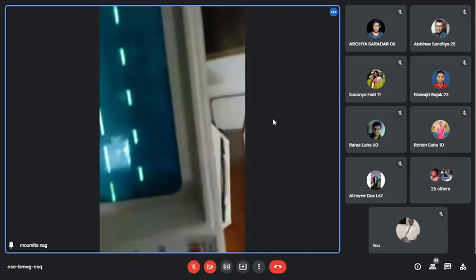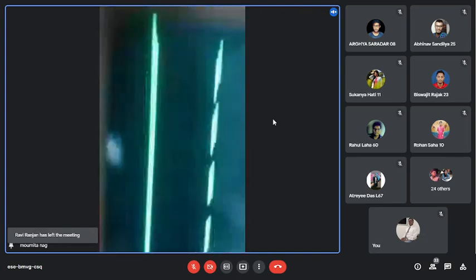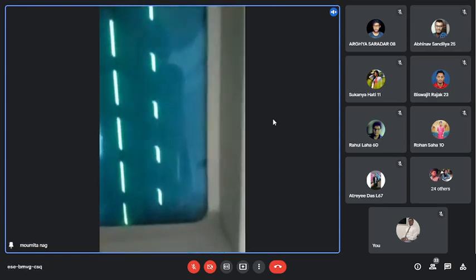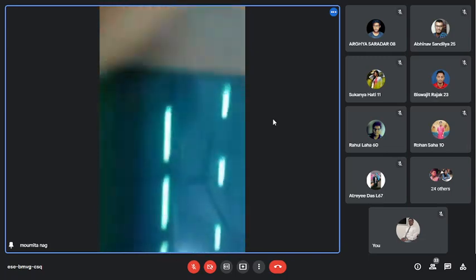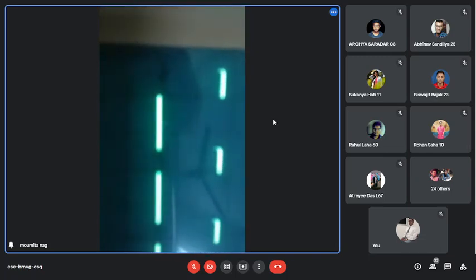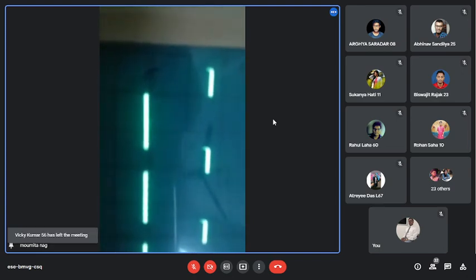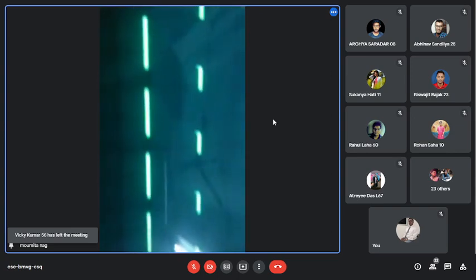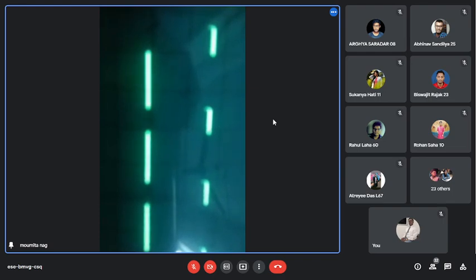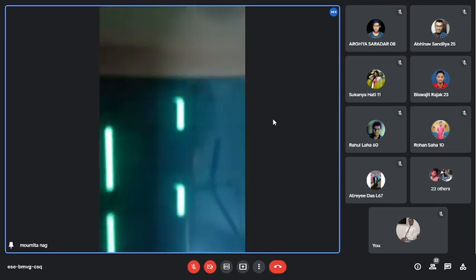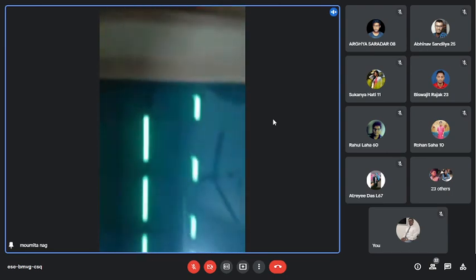Now I am giving the pulse signal. So what is the value of the pulse signal? It is 1 kilohertz and 10 volt peak to peak. For giving that pulse, this type of output I am getting at the timer 1 output. This acts as a carrier signal. You have to note this signal first. Draw this signal.